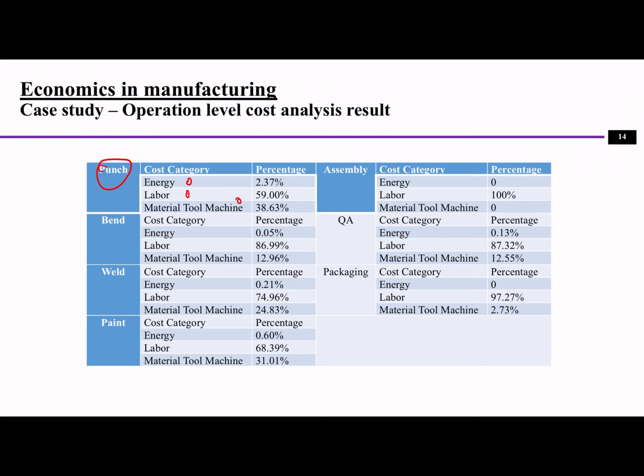So what I did was hook up some energy loggers on the machine at the power unit, and when it's machining, I record what the power is. When it's non-machining or on standby, what is the power, and when it's off, right? Also, you can compare the power difference in different situations. Another thing is you need to know the time: how long it is processing the part, how long it is standing by, and how long it's off. Based on all this information, you can calculate the energy cost as well as the labor cost, right?